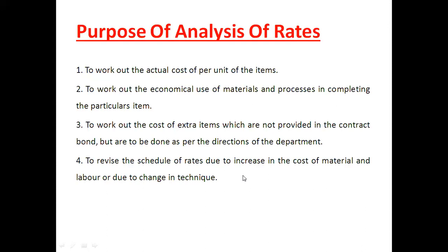Then the next purpose is to revise the schedule of rates due to an increase in the cost of material and labor, or due to a change in technique. If your labor cost or material cost is going to change due to some incidents or happenings on the site, environmental conditions on the site, then definitely you have to revise your schedule of rates. That means whatever estimate you have prepared, you have to revise it.